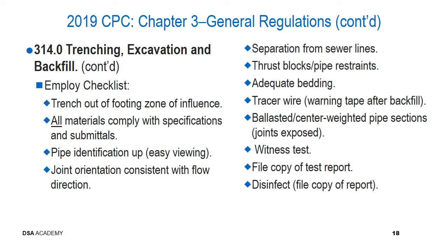There are times where your witnessing of a test is required to be documented on a form, such as the NFPA 13 form or the NFPA 24 form. Be sure and affix your signature and date that document on behalf of the owner and on behalf of DSA's representative witnessing the test, and get a copy of that test report and file that test report in the most appropriate folder in your job file.